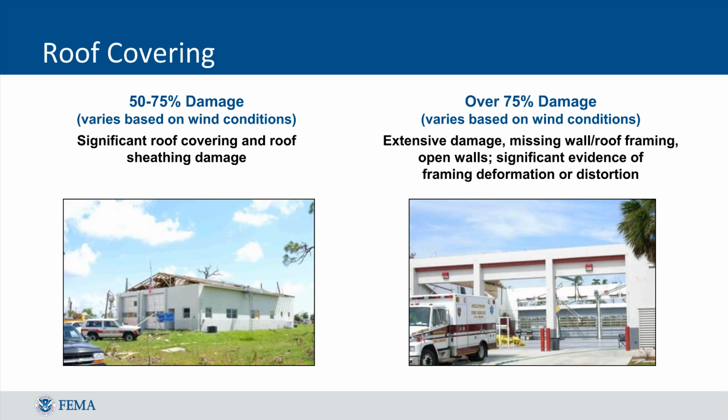Large sections of the roof may have been torn off by the wind in this scenario, but other sections may remain in place and cover parts of the structure, such that the complete replacement of the roof would not be necessary. When damage levels exceed 75%, most of the roof covering and sheathing will have been damaged or completely torn off from the structure. There will be major exposure of the interior of the structure to the elements, as the roof will be mostly removed from the structure or otherwise ineffective. This will result in the need for full replacement.